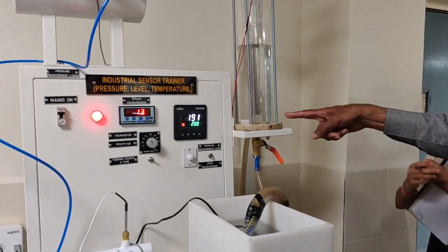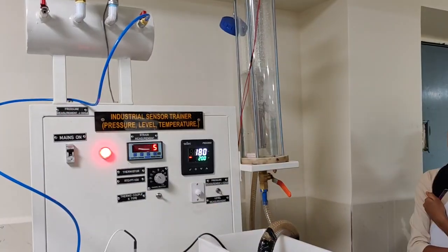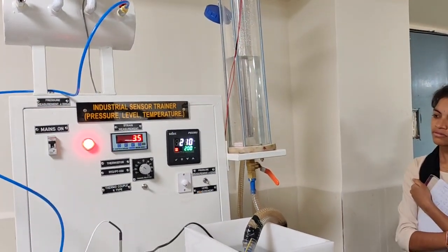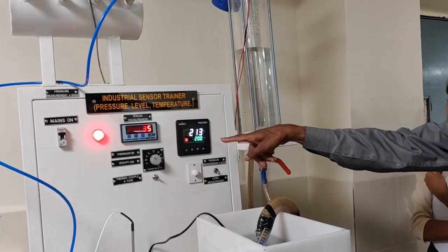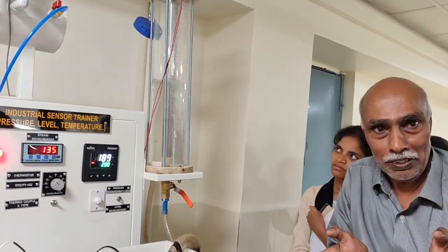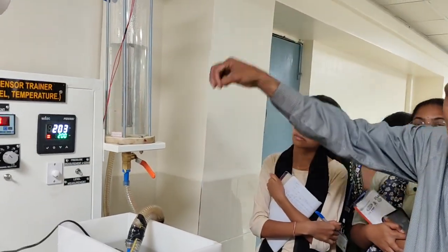Now you see 191, off. Now it is getting on. It is working in on-off. It's only on-off, not a regulation system. A regulation system is different. For that, you have to do the programming and use a regulating valve. A pneumatic operated control valve will be there. Those things have to be used. Whatever water is required, that much only it will feed.